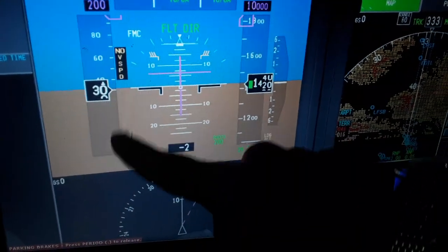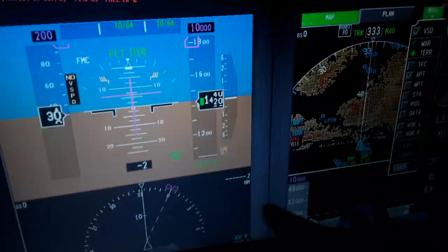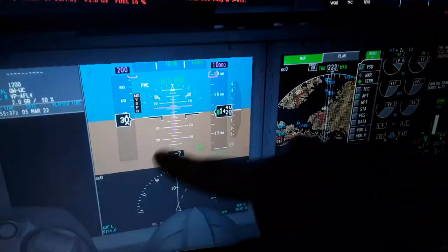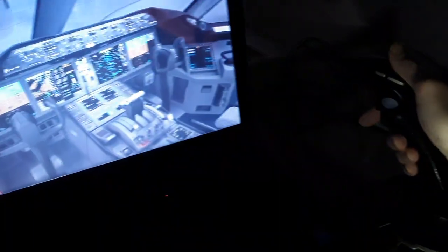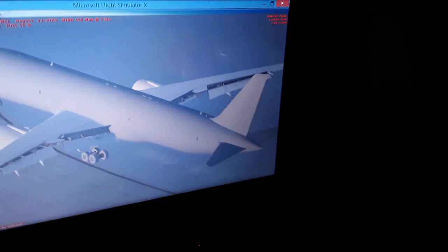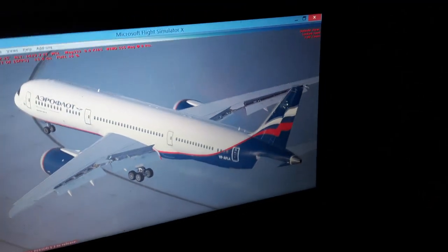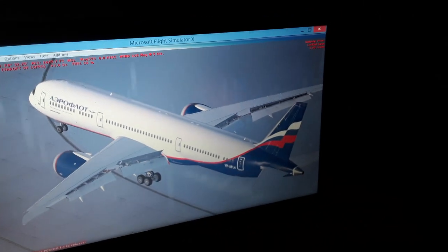So you'll see an amber or yellow and red indication here as the warning for the stall. We need to increase the airspeed, this is the airspeed tape, so we need to accelerate the aircraft, move the thrust levers forward and push the yoke or the side stick down until we exit the stall condition. So the airflow becomes detached in a stall for a given angle of attack and airspeed.